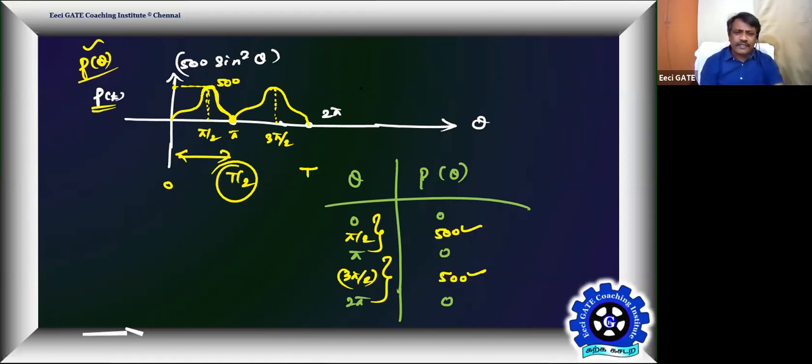Someone may ask you what is the frequency of your instantaneous power. It is double, because of sine square. If it is sine omega t, then sine square can be converted into the corresponding double-frequency form. We will see that next.